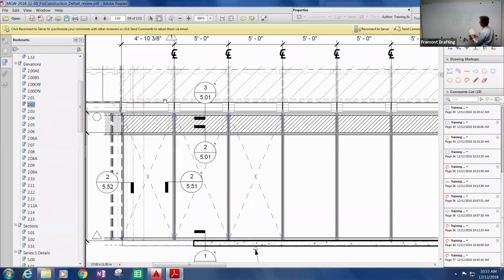But now let's say that translating element's over here on this side, and my anchor is right here and it's right here. So now as this pulls over, we've just run into each other on the one. And then when it goes back the other way, I'll have plenty of room over there and I'll hit on this side. So when we run into those situations, we have to design those substrate details to not have that issue. So either we can have larger joints, or, if products are recessed in, maybe products stop short of ours so that we eliminate that overlap.